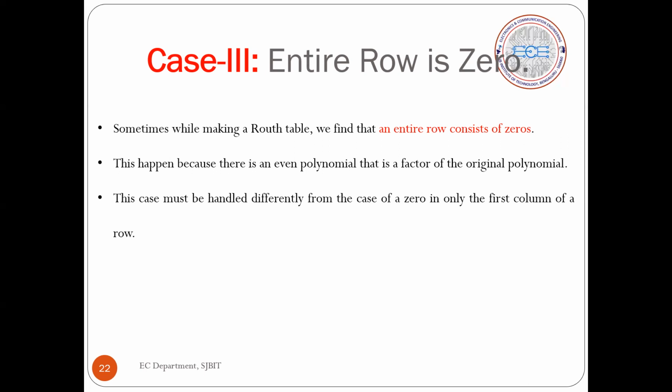We construct a reciprocal system, and we found that the reciprocal system will not allow the roots to cross the quadrant. The distribution of roots remains the same if you construct a reciprocal system. So by reversing the coefficients, the first element of a row becoming 0 can be avoided.